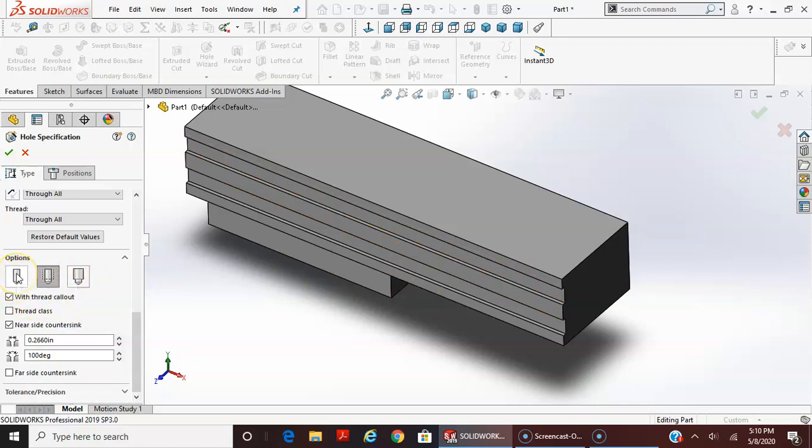And then this one is just the tap drill diameter, and this is kind of an old standard, because if you put the minor diameter of the thread or the tap drill size in your design, and all you had to do was specify that diameter of that tap drill size, which is also the minor diameter size, or falls within the tolerance of the minor diameter of the threaded hole, then the machinist can just look at that tap drill and look up on the chart, and based on that diameter he would know what thread you're talking about.